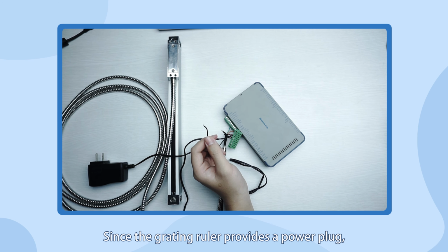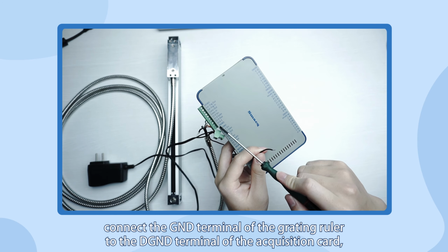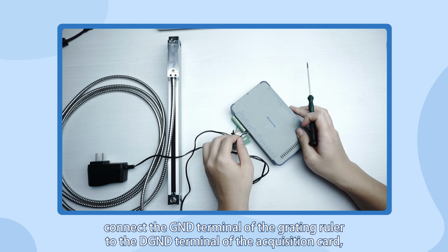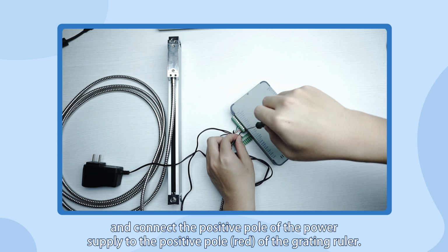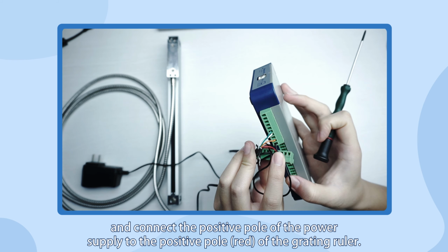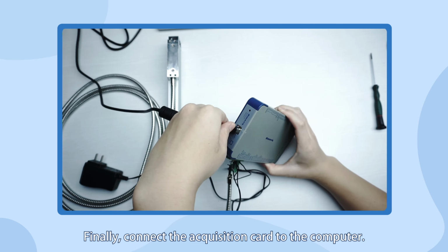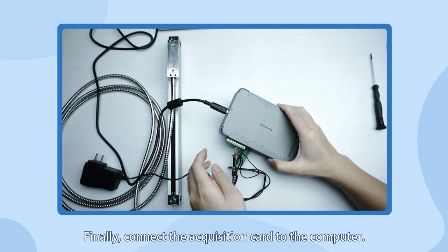Since the grating ruler provides a power plug, connect the GND terminal of the grating ruler to the DGND terminal of the acquisition card, and connect the positive pole of the power supply to the positive pole of the grating ruler. Finally, connect the acquisition card to the computer.